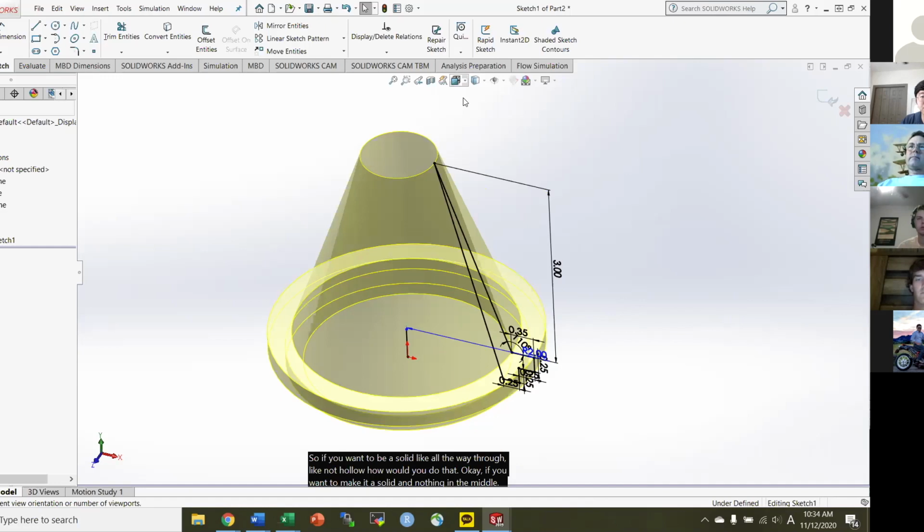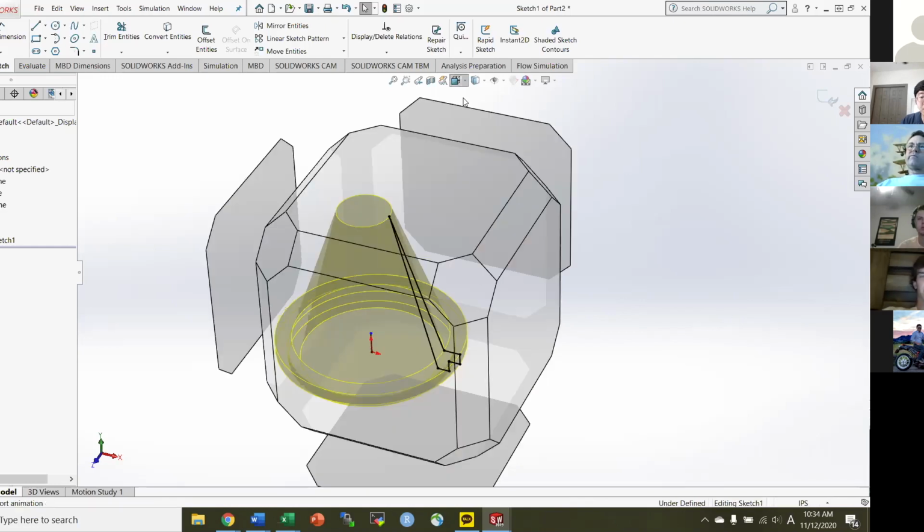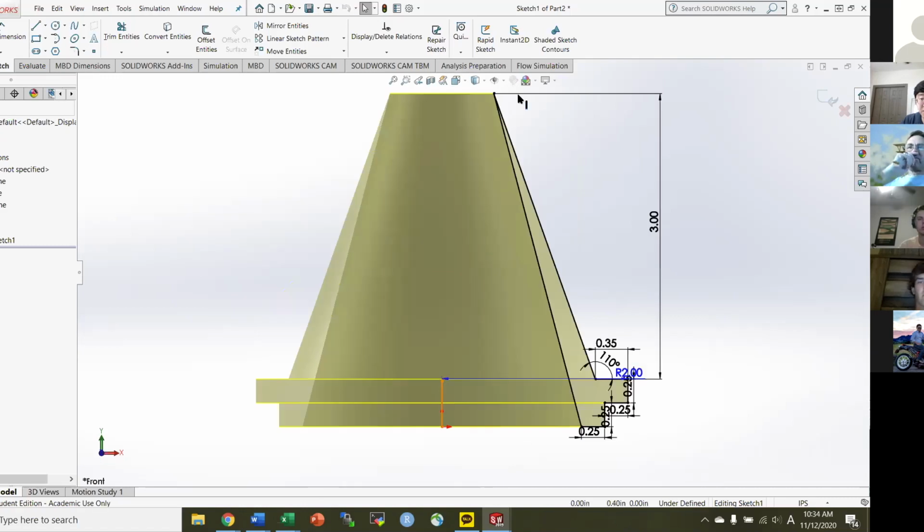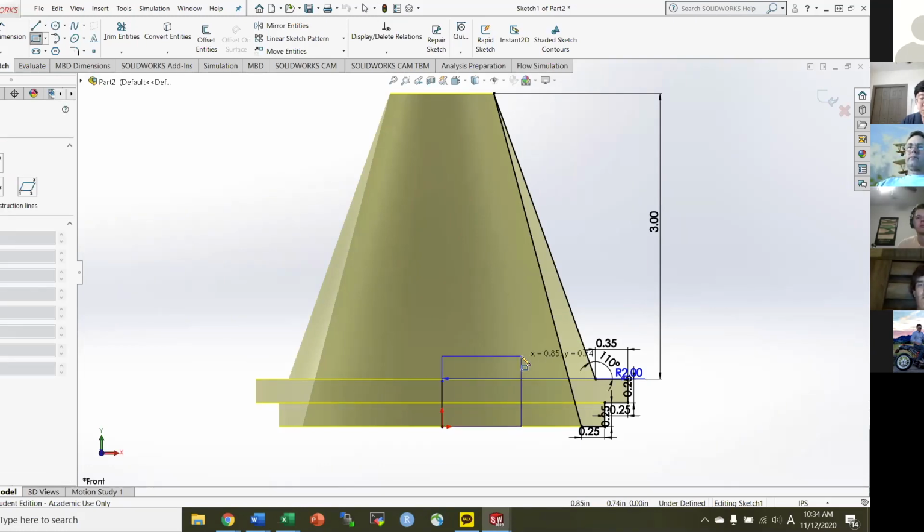you see the front sketch that I created, you can see there is some distance between the axis of rotation and the model that I created. So if you create a rectangle and you start from the origin, and then go a certain distance, and then you rotate it, then there will be no hole.